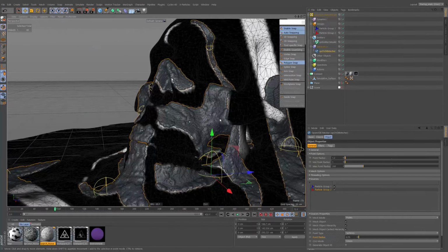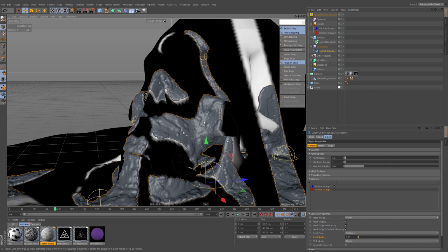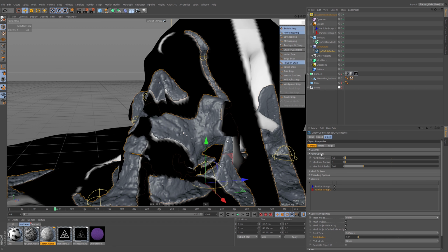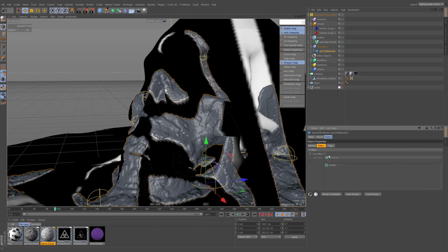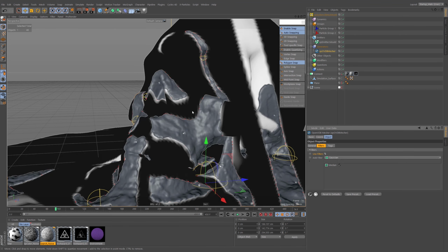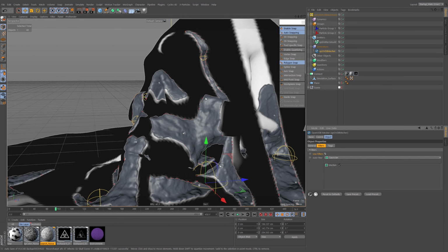That's quite dense. You can work with much denser meshes than this, but I think that's going to be fine for our purpose, especially once we've worked a little bit on the filtering. Now, the filtering really depends on what you're doing, but it tends to have a bigger impact if your voxel size is higher. If we went to a finer voxel size, you're going to need to add more filtering iterations. So we jump to the filters here, and what these do is they essentially filter the source voxels so they're smoother.